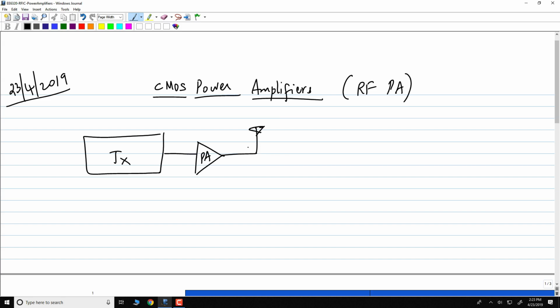So the first thing is that, I'll show it like this. So this is of course the diplexer or duplexer. Okay, a diplexer is normally a duplexer that operates with different TX and RX frequencies. If the TX and RX frequency are the same, then it's officially a duplexer. People were a little bit more loose with language till a few years ago.